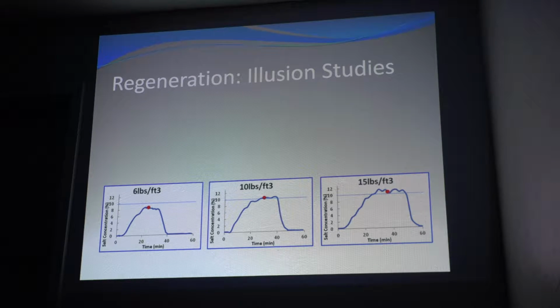What happens here, you will get more capacity per pound of salt, but you don't get the high resolution of soft water with it. So like I mentioned earlier, on residential applications, you can get away and really be satisfied with under a grain of hardness, under 17.1 parts per million, okay?